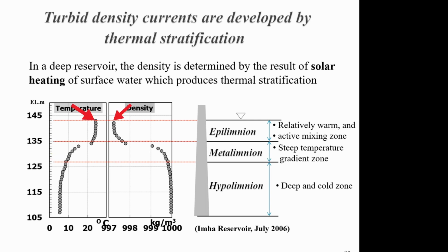So you get a difference here in density: you go from 1,000 at 4 Celsius down to 997.5, right? That's in kilograms per cubic meter. So what does it mean? It's my anchor point, a rule of thumb, a little number, my benchmark here. It means that the lighter water stays on the surface, but I could add sediment on top, right? And then if I add sediment, the density would go up.